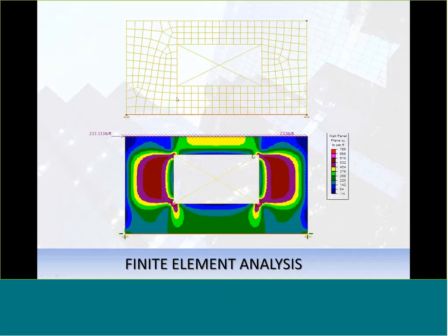So you can just drop in openings and drop in your wall panel. It automatically will mesh this opening for you. So when you apply that load, the loads are going to distribute inside, and you'll see the forces in these plate elements as contours, but you don't really have to do much past that. You can visually see it, which is a really great confirmation of what's happening and how the forces are flowing through your walls. It tells us what is happening in that wall.